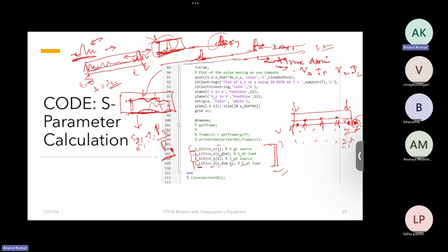An interesting analysis could be if you have made a filter: you can analyze which signals get filtered by just recording the voltages at each point, performing an FFT and seeing which waves reach till which node. So these are things which I played with when I started with FDTD. Maybe you guys can try that as well.